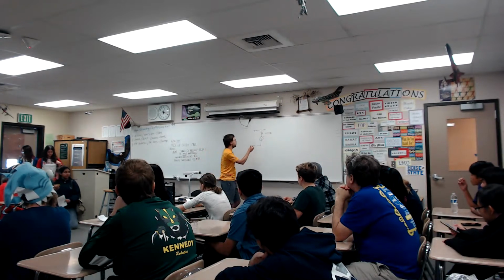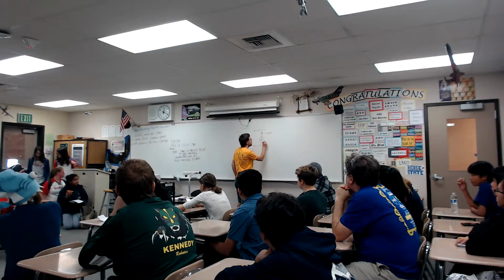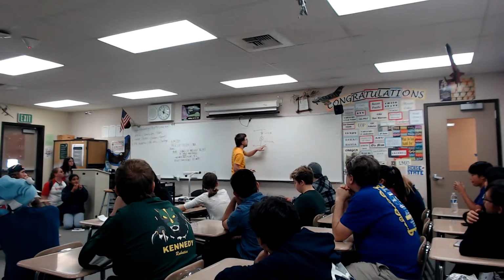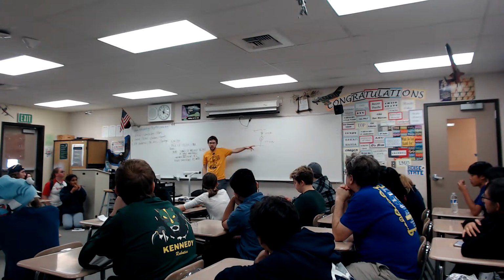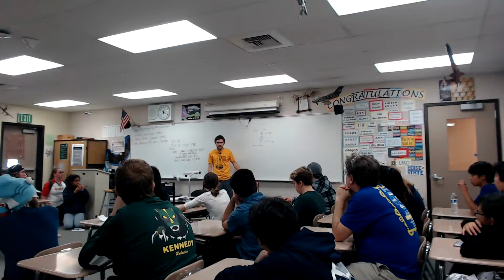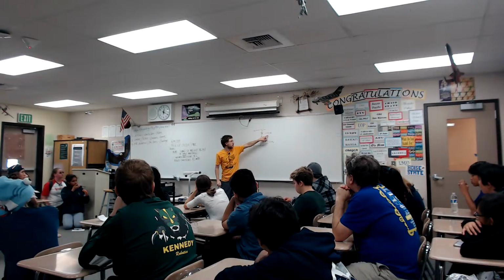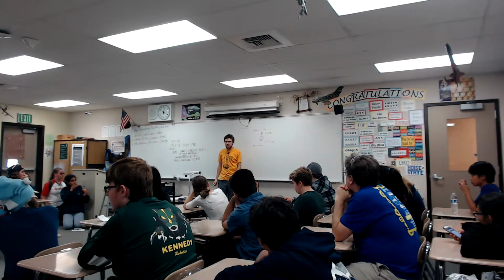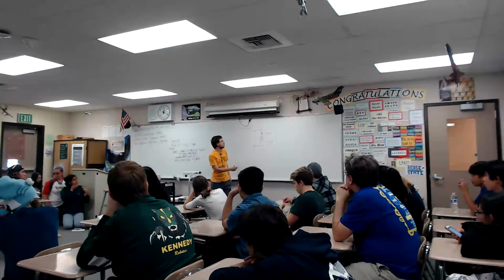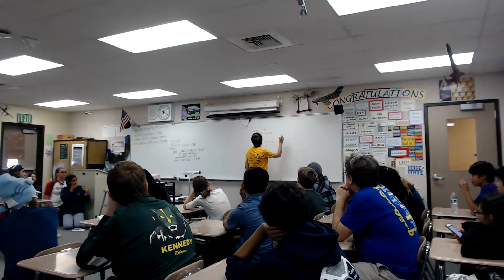And then the voltage across the generator, V equals omega times our voltage constant. This should be decently familiar. If you put more voltage in, it's going to go faster. And with more voltage, you can also get more current. And the resistance is the copper in the windings. So we can put this together, and we have our motor equation.